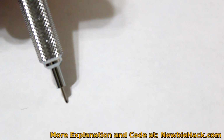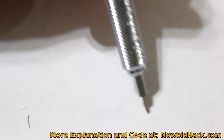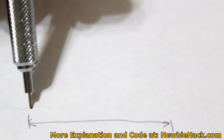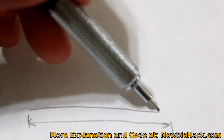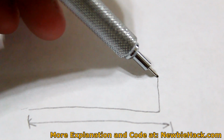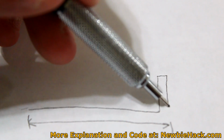There's a couple of ways we could actually create the PWM, and that's in code. We could say, let's say we wanted to do 1 millisecond for a 20 millisecond period. So in our program, we could say, okay, wait for 19 milliseconds, and then at the 19th millisecond, we put a logical 1 to the pin that we want to output, and we'll do that for 1 millisecond, and then bring it back down.